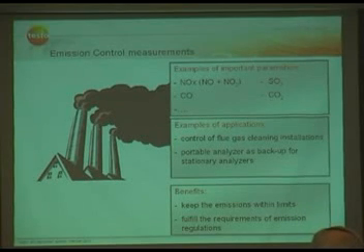So that means every sensor like CO, NO, SO2 has to be calibrated before the measurement, and then they perform the measurement. And then at the end of the measurement, which can be within 24 hours, they have to recalibrate the analyzer just to show that there is no drift or nothing happened to the sensors. And then they are fine and can use the readings as an official measurement.